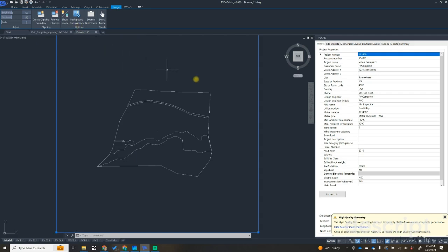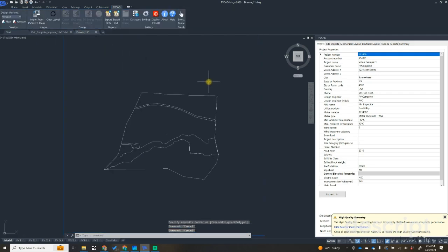actual visibility of it. And very quickly, just because I know there's a lot of different experience levels of CAD users out here, you'll notice I clicked to select this. I clicked to the right of it with a left click, and then I dragged to the left, and you can see as soon as I encounter an object going from right to left, it will go ahead and highlight that object. If I were to go ahead and left click on the left and go to the right, you can see I'm encountering that object, but it's not highlighting it.